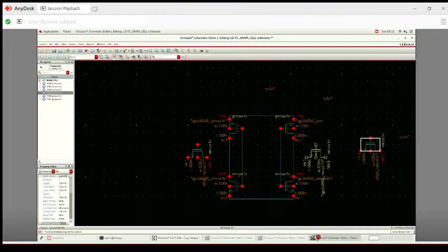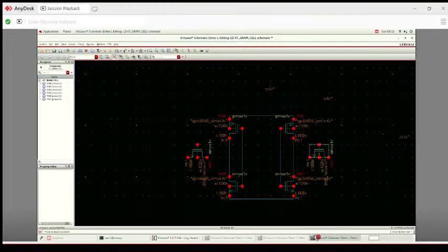Yeah, it's done. Okay, so now it's at a simpler distance. Here the body terminals of both access transistors are not connected with the sources, because their sources will be connected with bit line and bit line bar. But we require the bodies to be connected to ground, so we will not connect the body terminal with the source. Let's move forward.